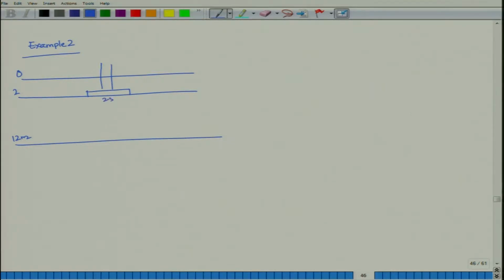This is your 2.5 meter, gamma is your 18 kilonewton per meter cube, and the profile is given, the N value profile is given. SPT N 0, 10, 20 and this is your 30 SPT N. So, it comes out to be N average equal to 15.